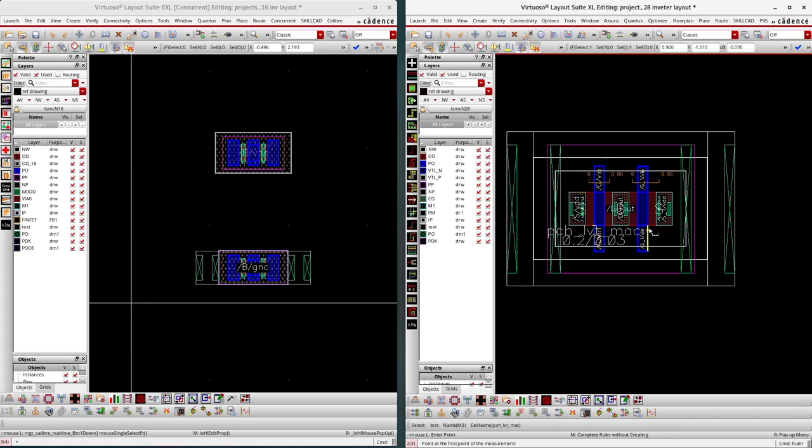We don't have any other extra poly layer here, only the first finger and the second finger, with a gate length of 13 nanometer. Since it is a 2 finger device, we have a source terminal here, then a drain terminal, and then again one more source terminal. Followed by the source terminals, our primary and secondary dummies are available here.